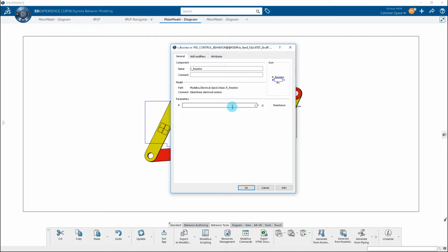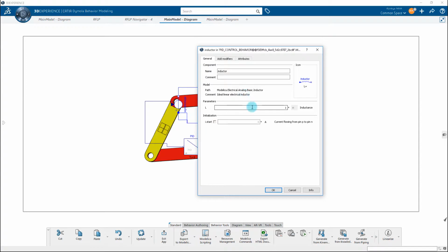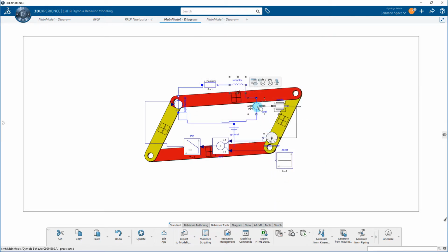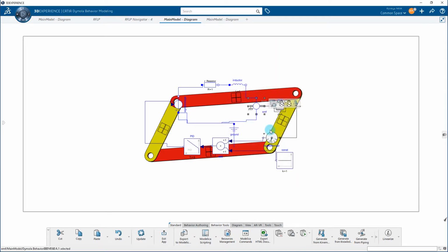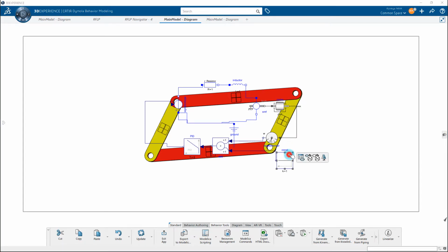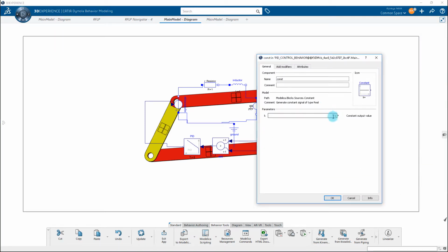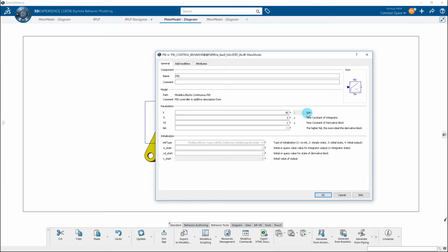The mechatronics engineer adds mathematical models for the controller, DC motor and power electronics. The engineer can then change the parameters of these models. The mechatronics engineer can create a separate library for mathematical models of such components and use it directly in the mechanism. By adding such desired components from the libraries, you can easily optimize existing systems. Different controller designs like PI, PD and PID control can be tested. PID values have to be tuned to obtain good dynamic performance. The physical product can be modified after simulations.